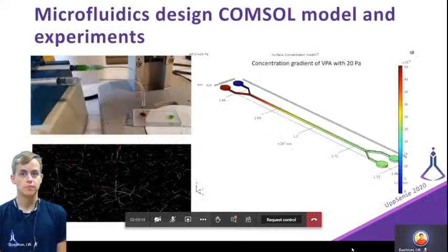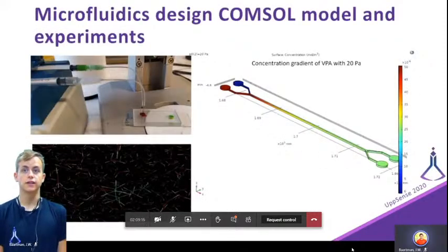To start off the analysis, the plasma sample is injected into a microfluidic chip, which by laminar flow diffusion separates the BPA from the plasma phase into a secondary buffer phase, which effectively cleans the sample from larger molecules. Using COMSOL Multiphysics modeling software, we have been able to optimize the flow rate such that we maximize BPA diffusion while minimizing the diffusion of blood protein and reagents.